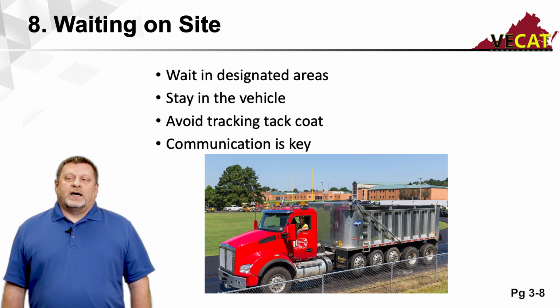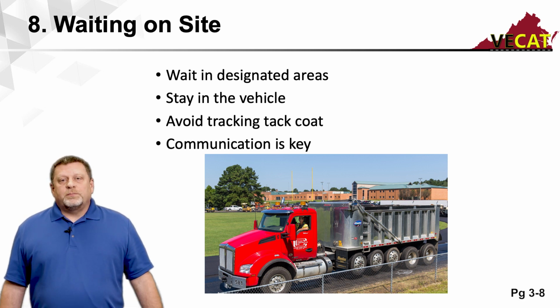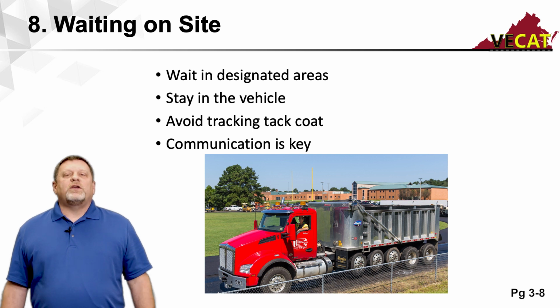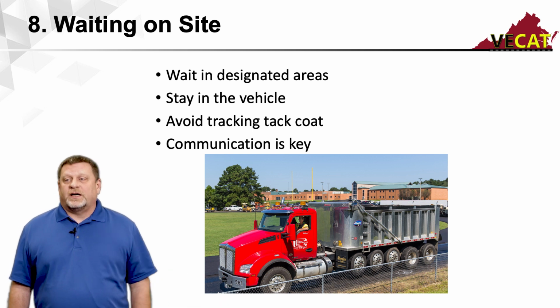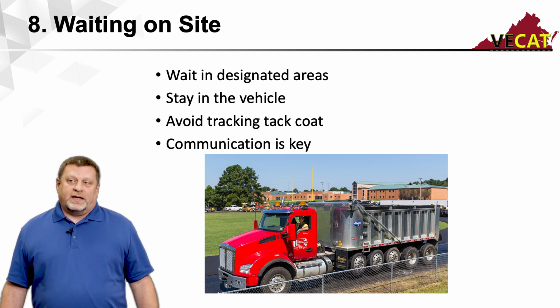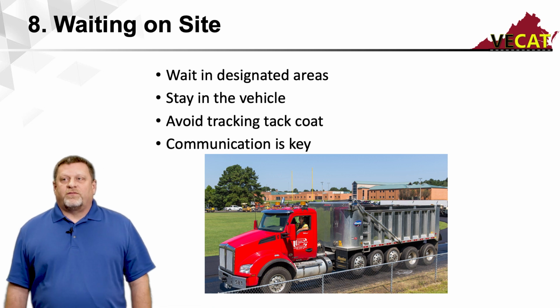Waiting on site. On some projects that are large enough, if you do have multiple trucks at the job site, you don't want them all lined up in front of the paver tracking the tack. That's a bad thing. Tack was placed there to bond and glue the two layers together. So the last thing you want is to have it stick on your tires and pull it off the job site. It creates a mess, and it's not doing what it was applied for.